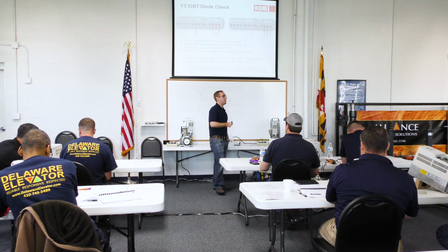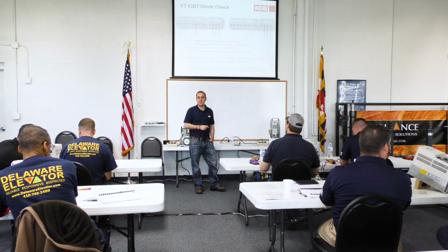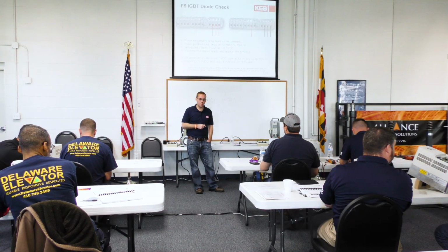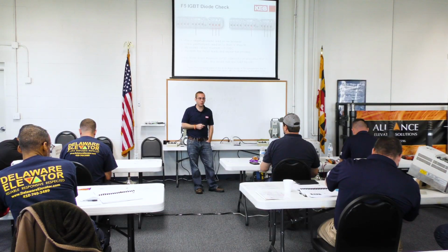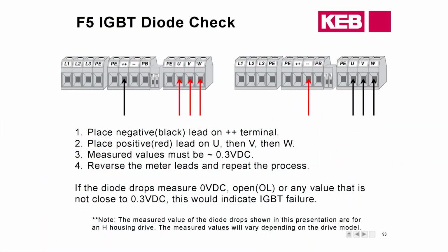So again, this is something that you can do in the field. You can determine which phase is bad. Again, this is something that the KEB service department would have to take a look at. And then we have the other direction. You'll take your red lead, put it on the minus terminal, take the black, and go to U, V, and W, and you should see approximately the same readings.